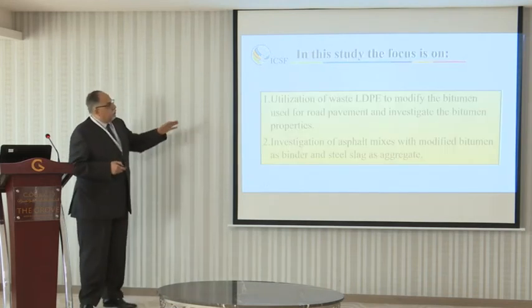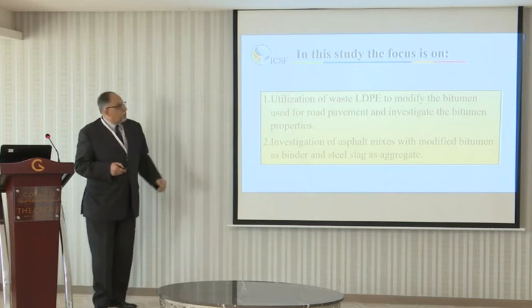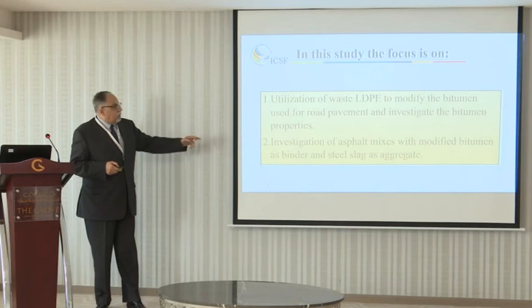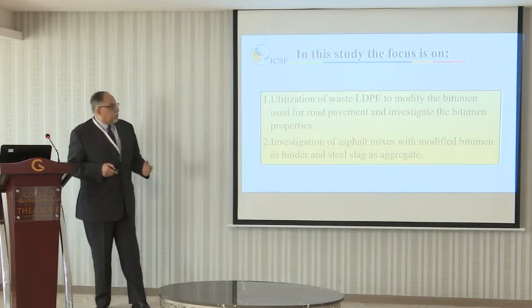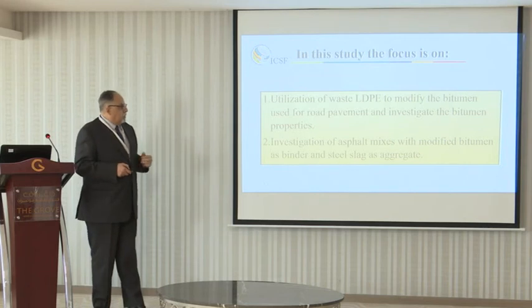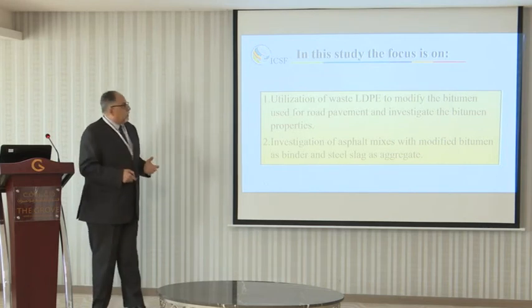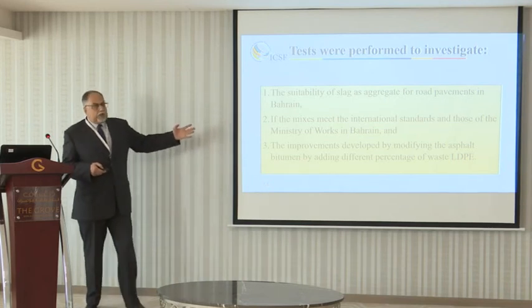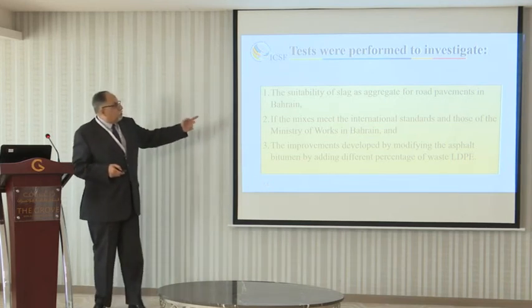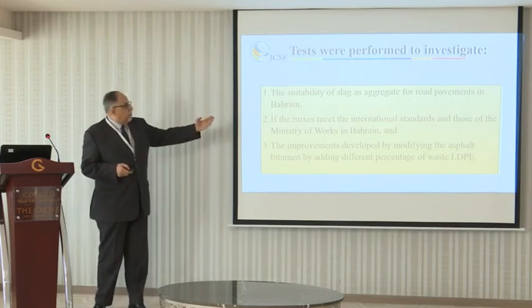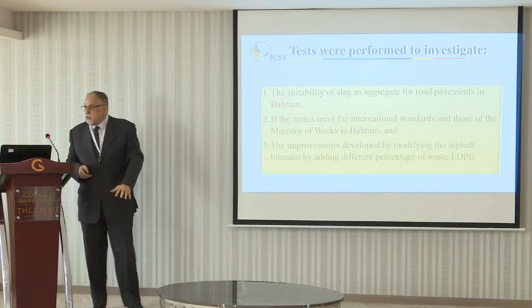In this study, we focus on utilizing waste LDPE to modify bitumen for road pavements, and also on investigating asphalt mixes with modified bitumen as a binder and steel slag as aggregate. The test was done to investigate the suitability of slag as aggregate for road pavements in Bahrain especially.